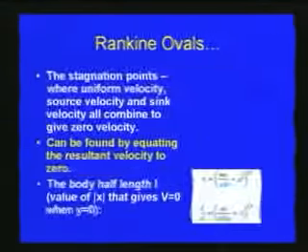problems. But as I mentioned, we should be careful that here we are assuming the potential flow theory, so we should be very careful in the use of these superposition techniques, especially while determining certain parameters like drag, lift, etc. It may not predict them properly, so we should be careful in the usage of this potential theory and these kinds of superposition.